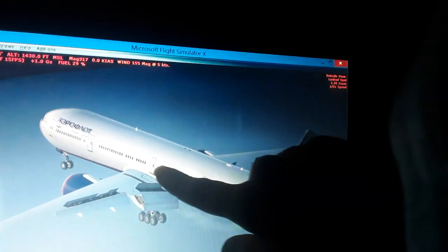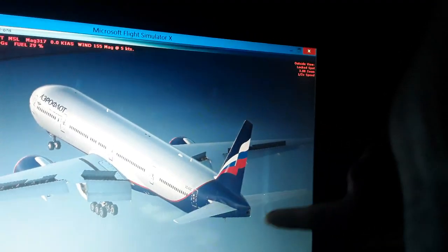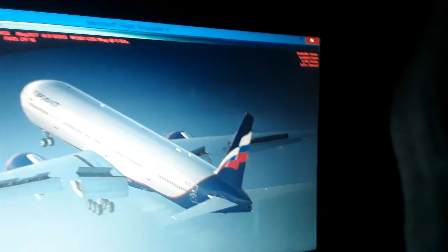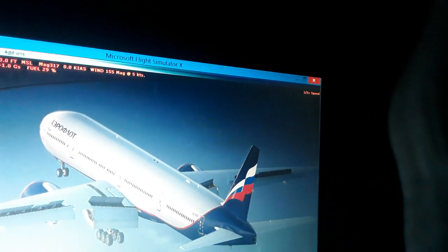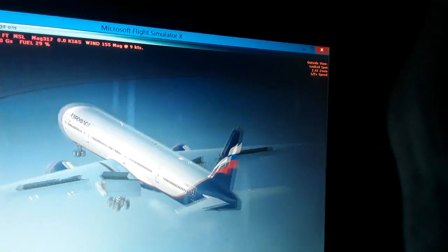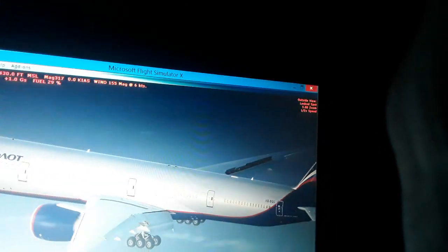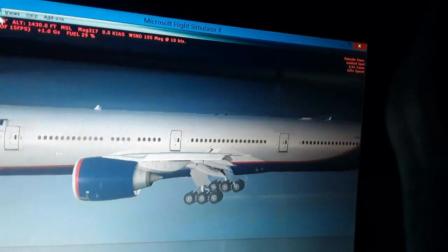So it's the lever arm times the distance from the center of gravity all the way back to the horizontal tail, over the surface area of the horizontal and vertical tail, times the airflow of the air mass per second, times the elevator deflection up and down, or the rudder deflection, or the ailerons and the spoilers, and times the acceleration of earth gravity depending on where we are in the world. So you have the force that can pitch the aircraft up and down, and also make it turn left and turn right. You can also see the wings of the aircraft produce the aerodynamic lift holding the weight of the aircraft.